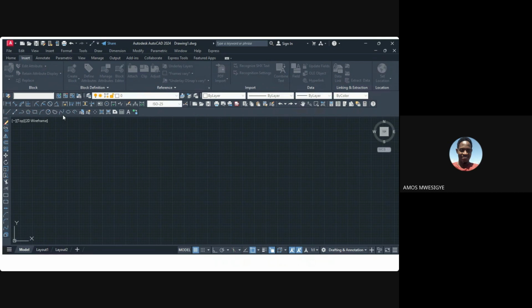So before importing your PDF, it is a must that you first look at that PDF before importing it. You know where your floor plans are. You know where the sections are, or the elevations. So we really need the floor plans. It's what we are going to deal with. So I would select, let me say, page 1. It's where I'm seeing the floor plans. So we import, we press OK.